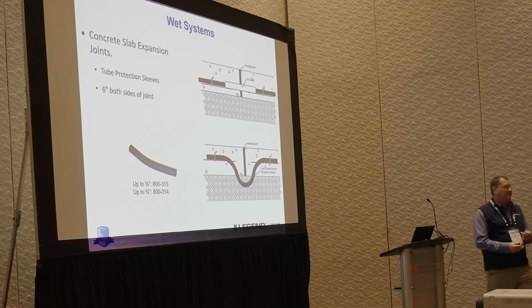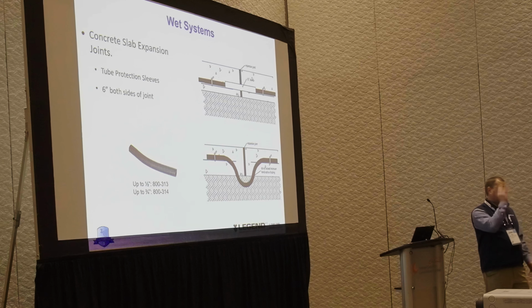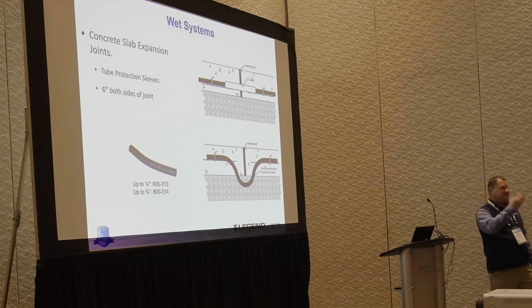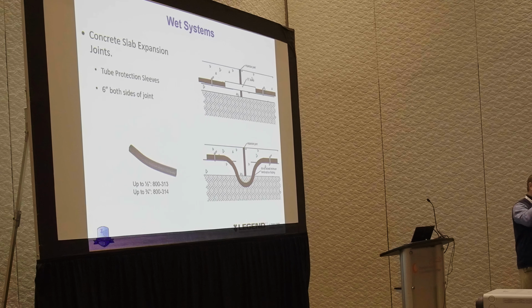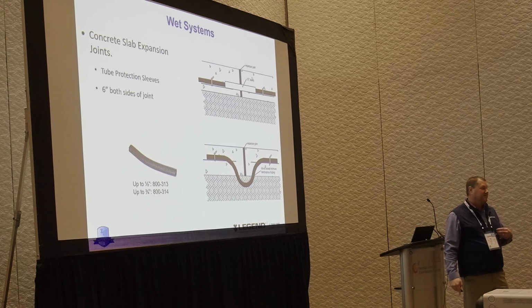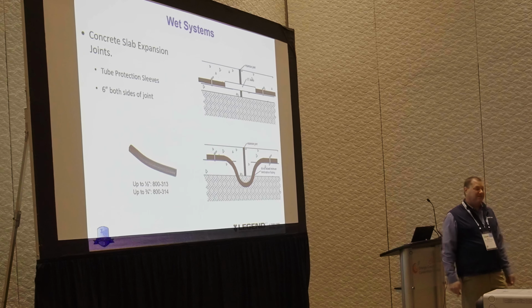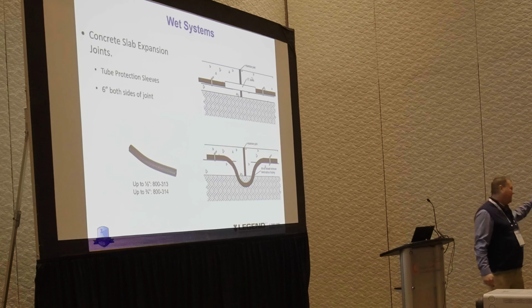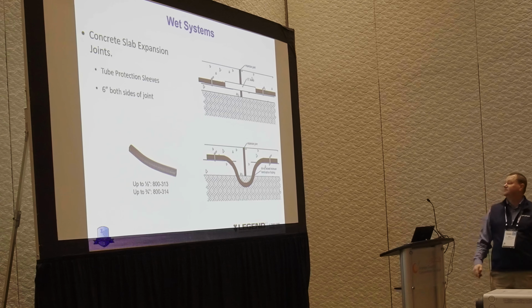Usually on a commercial print, if you're quoting a commercial job, they're going to show you where those expansion joints are. Not the control cracks necessarily, but those true expansion joints are there, and we're going to design around them. We're not going to have 60 tubes running across that joint. We're going to run the tubing parallel to it so that we're not crossing that joint as often. Unfortunately, sometimes as designers, we may not know where that is because it's not in the print. So again, if you find out, hey, it would be really good if the tubing was running the exact opposite way, you can call your designer up. If we're using LoopCAD, it's not that difficult to push a button and let it run the other way. And then you can have a drawing on the wall that exactly represents what you're putting in.